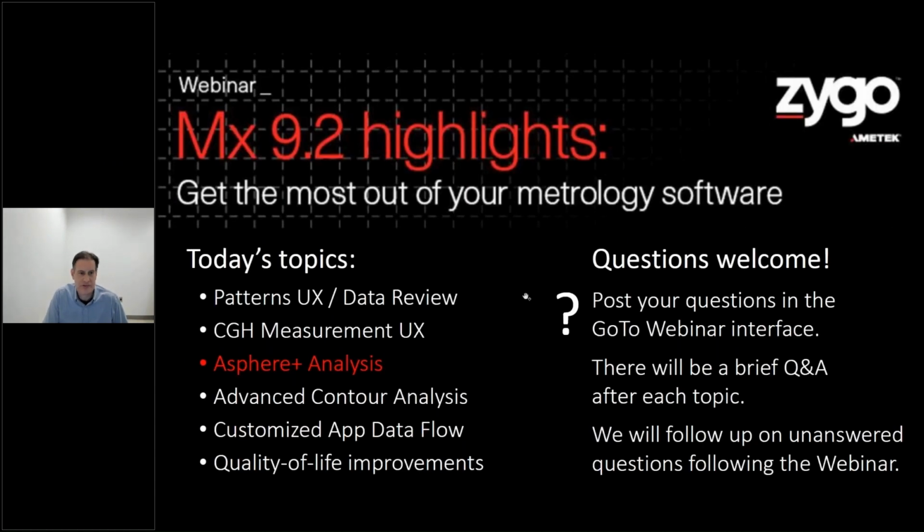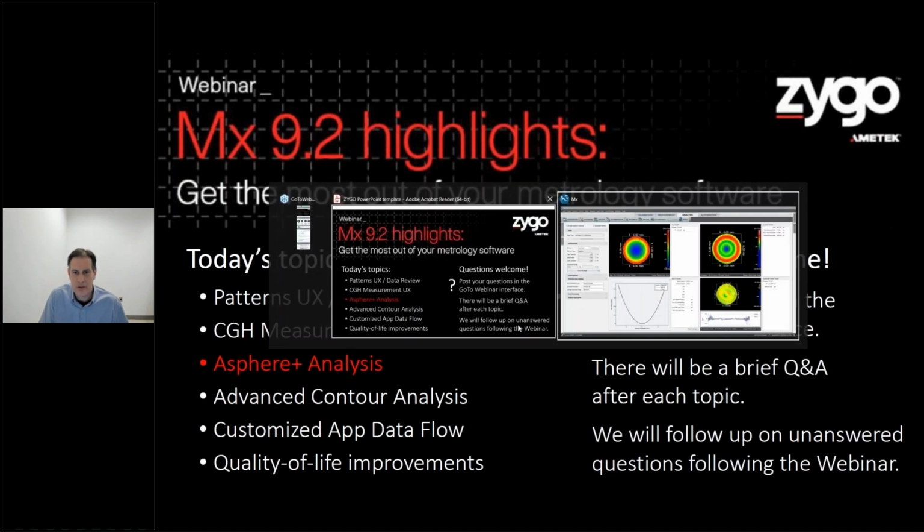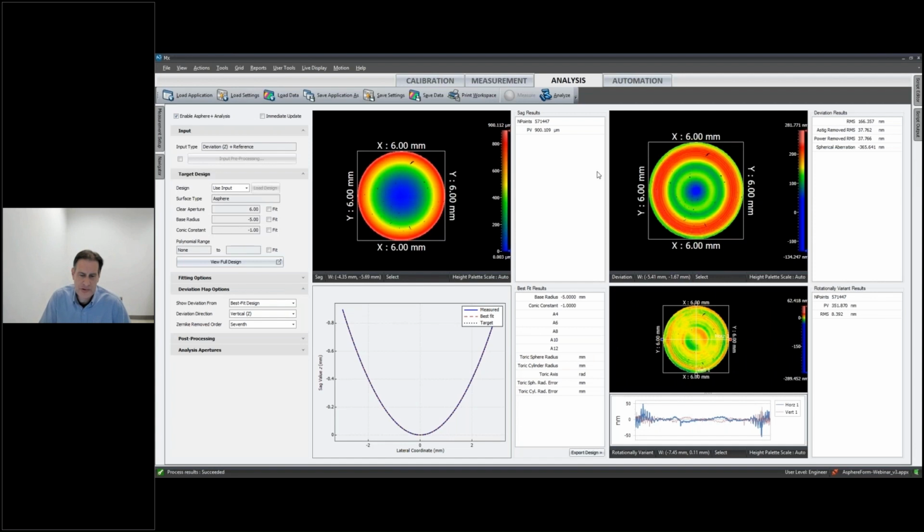Okay, so next we're going to discuss Asphere Plus analysis. And for that, I'll just show this screen here. This refers to an analysis which can be done to fit and remove prescriptions from measurements of what I'll call Asphere Plus parts. So these are parts that include aspheres, torics, biconics, generally parts that have a prescription with some degree of symmetry, but even some mild freeforms. And this supports measurements from VFA Plus, from CGH, as well as from optical profilers. So as much as possible, it is instrument agnostic.